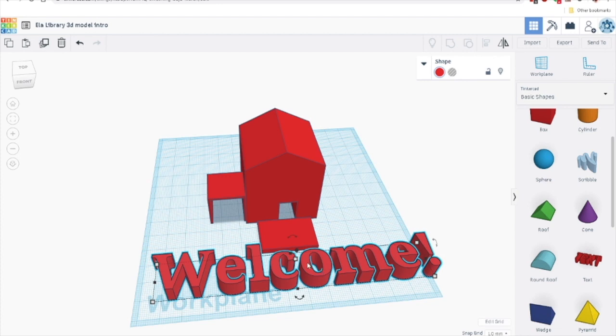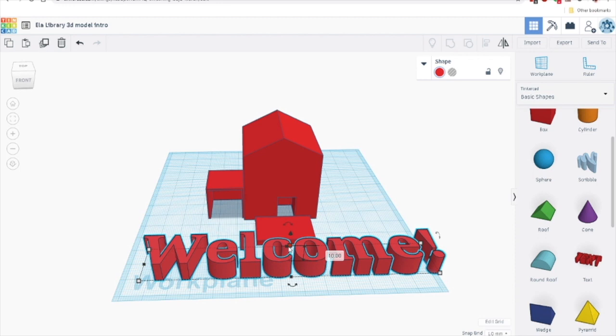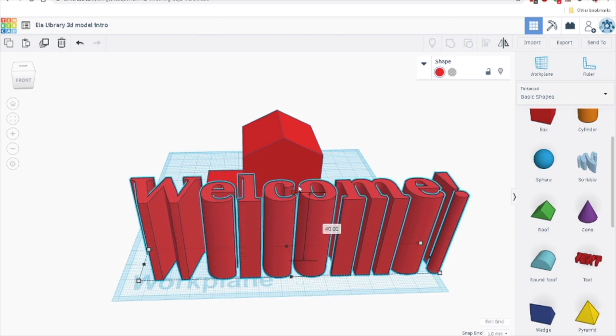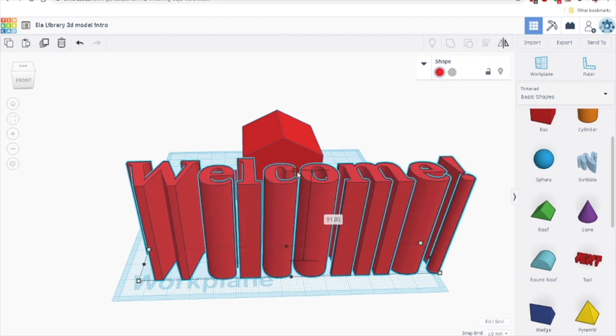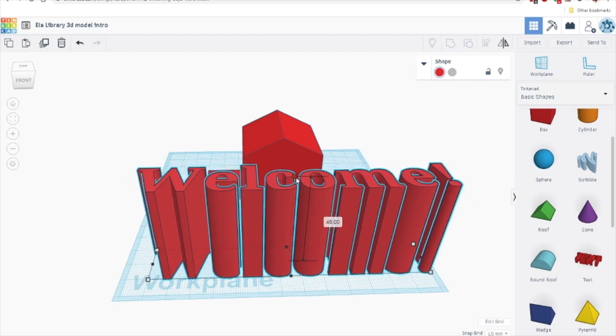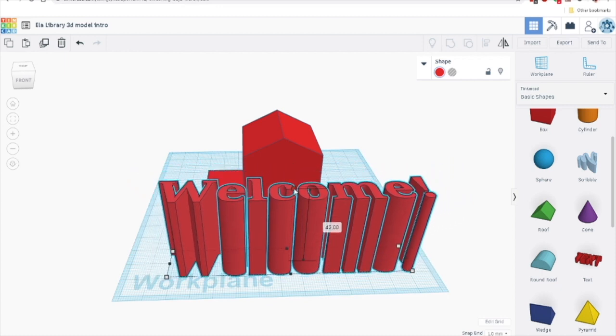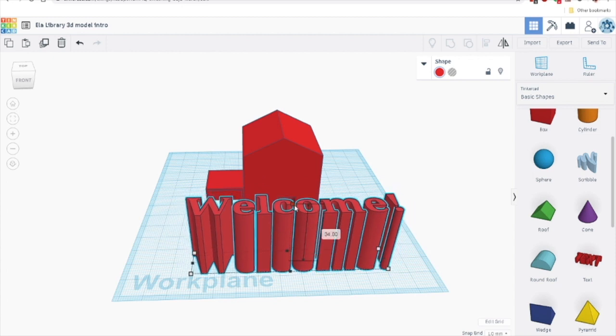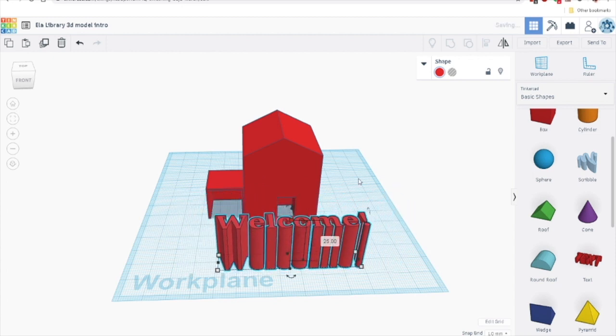So the first thing we want to do is click on the height. Right now it's set to 10. We're going to lift it up to like 50. 51's fine. And then we're going to hold the shift key on the keyboard, and left click and drag on that height again, and drag down. What you're going to see is the width and the length are also changing at the same time as the height. This is changing proportionally.